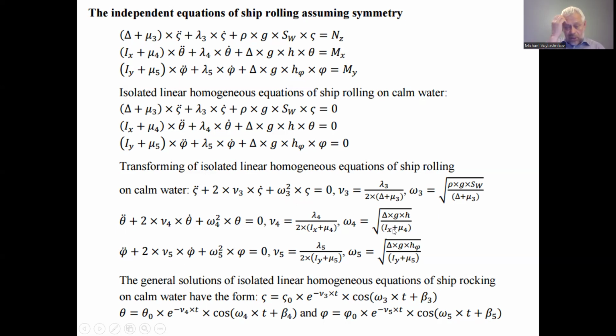In the determination of the natural frequencies for the ship vertical rocking, ship rolling, and ship pitching, the characteristics of inertia are their own moments of inertia, relative to the abscissa axis, relative to the ordinate axis, for example, and the added mass relative to the same axis. We use only one index due to these simplified equations.